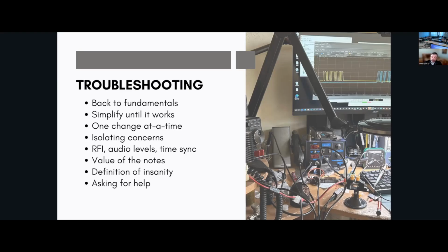That includes accessory cables, so an interface like a Digirig or any other interface connected to the radio. The antenna will try to use the shell on that accessory cable as part of the counterpoise system, inducing pretty high RF voltages in it, and that will throw things off and break communication. So RFI is something to look at. The solutions would be the choking, counterpoising, and improving the antenna overall. These are discussed in detail in the support material.